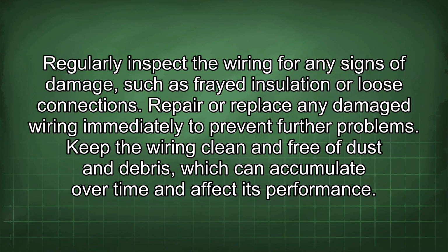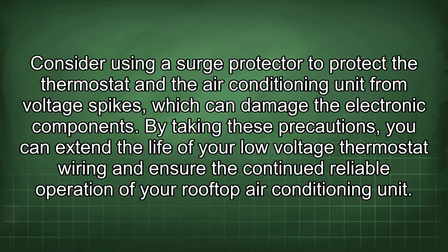Regularly inspect the wiring for any signs of damage, such as frayed insulation or loose connections. Repair or replace any damaged wiring immediately to prevent further problems. Keep the wiring clean and free of dust and debris, which can accumulate over time and affect its performance. Consider using a surge protector to protect the thermostat and the air conditioning unit from voltage spikes, which can damage